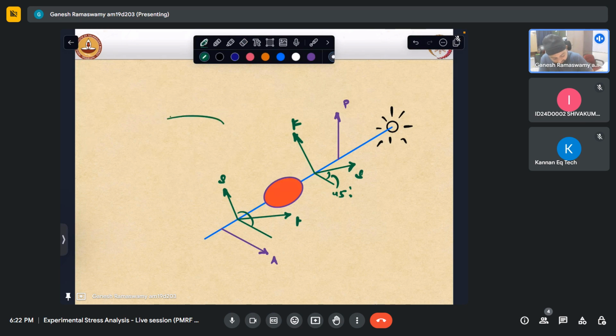Here we will be seeing only isochromatics because the output light intensity now is I. I have kept this analyzer at 0 and it is crossed, and the quarter wave plates are also crossed. So I'll essentially be seeing Ia sine square delta by 2.